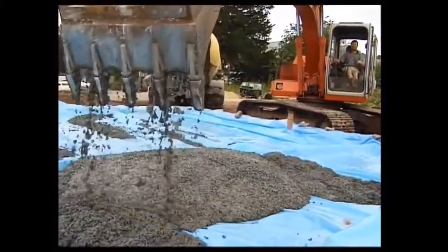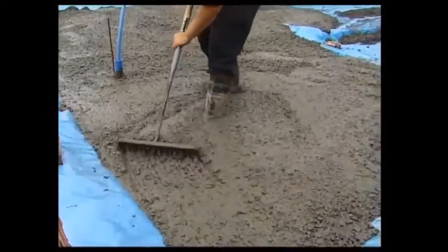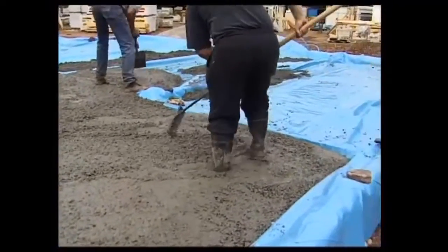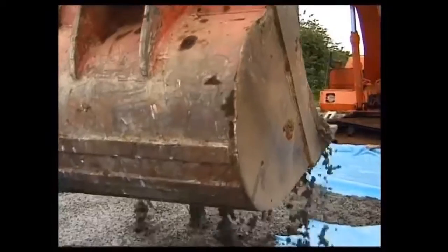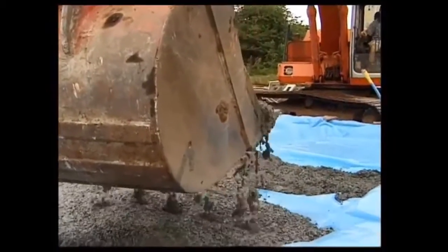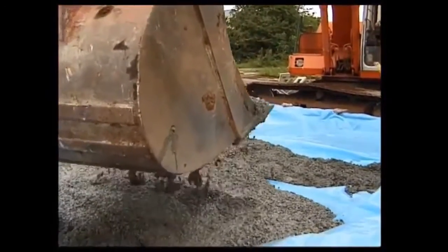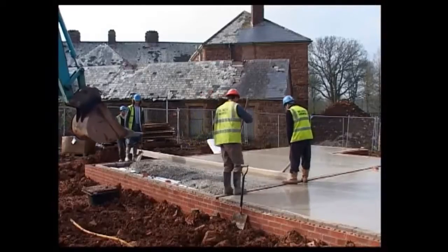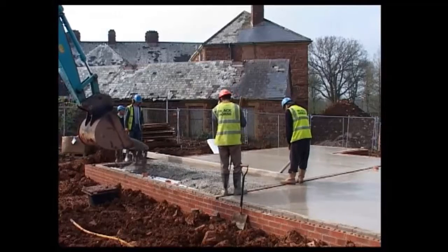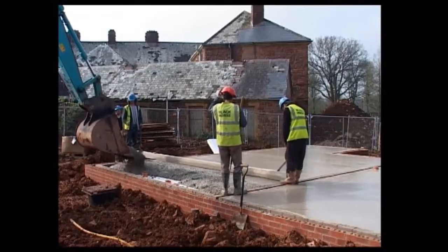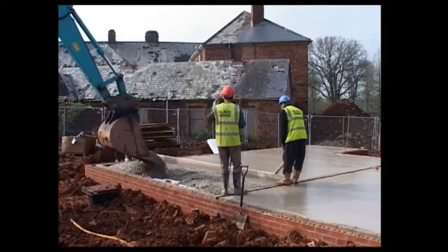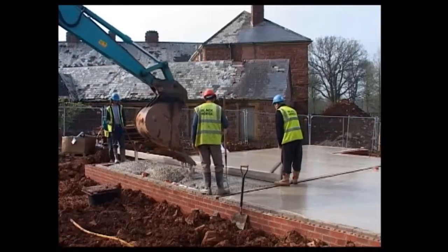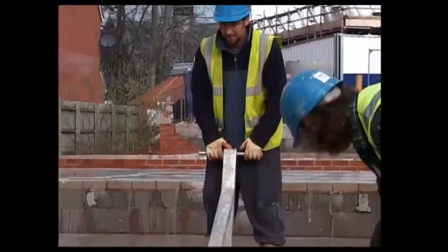The concrete is usually brought onto site ready mixed. It's a mixture of cement, stone and sand and can be produced in a variety of strengths by varying the proportions of the ingredients. When the concrete is in place, it has to be levelled and compacted. This is usually achieved with a heavy beam known as a tamp. Tamping levels the surface and expels surplus air and water. A tamped finish is fairly level, but not smooth enough to take vinyl tiles or carpet coverings.